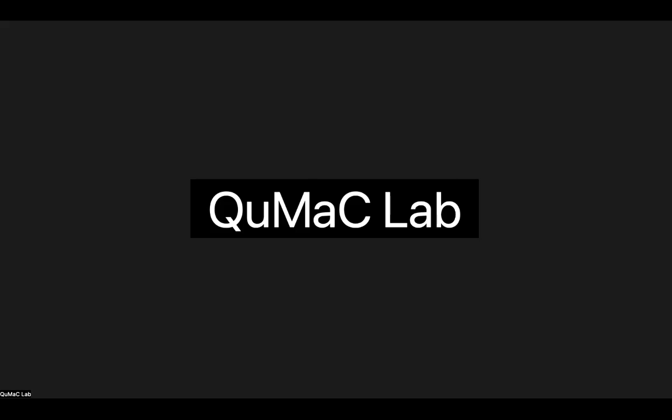You can now have a setup like this. Let me see this one. Let's look at this one here. So each of these circles with the cross is a standard 3-port mixer. So you see the L, I, and R marked here. The IQ mixer is a 4-port device which uses 2 3-port mixers which are combined in the following way.